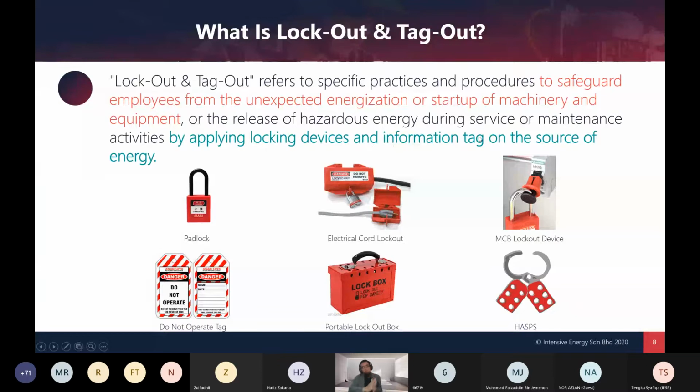During my time, I always said it's best if you can lock out, then tag out, both on your energy isolator. But if you can't, at minimum you can either lock out or tag out, depending. Lockout is always best. Once you lock out, people cannot operate. But if your design does not allow you to properly lock out, then a tag is the minimum requirement.